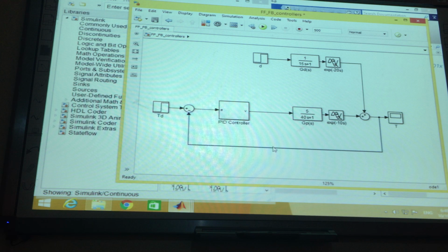And also, one of the objectives of having a PID controller, for example, if you look at the steady state value, it was 5, right? I would like to make it what? 1. It's not necessarily 1 actually, it depends on the desired value of the temperature. So I wanted actually to follow a certain value. In the open loop control system, it can succeed for the first time to do it, yes? But if you add any disturbances later on while the system is in operation, it cannot handle it because it's blind, it cannot read. There's no sensor, no feedback from the controller or from the control system to correct this value or the change that happened to the output.